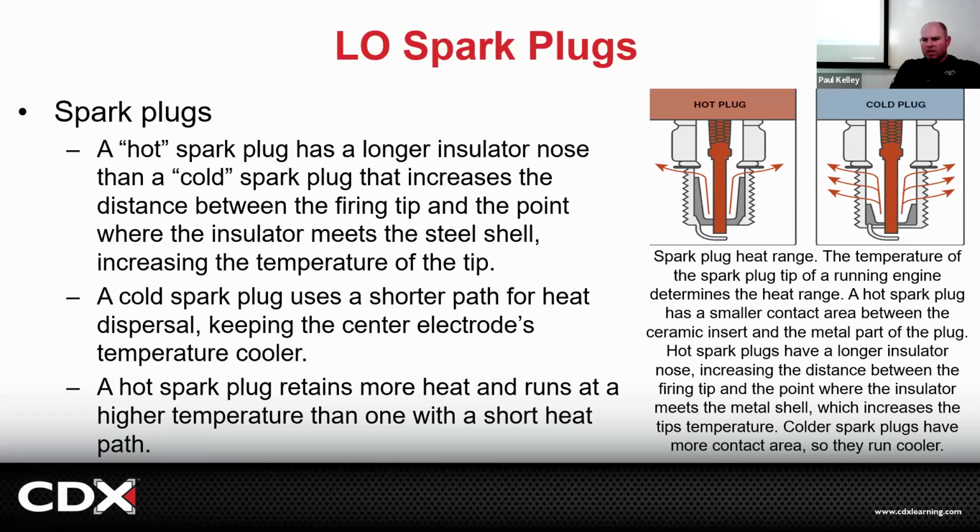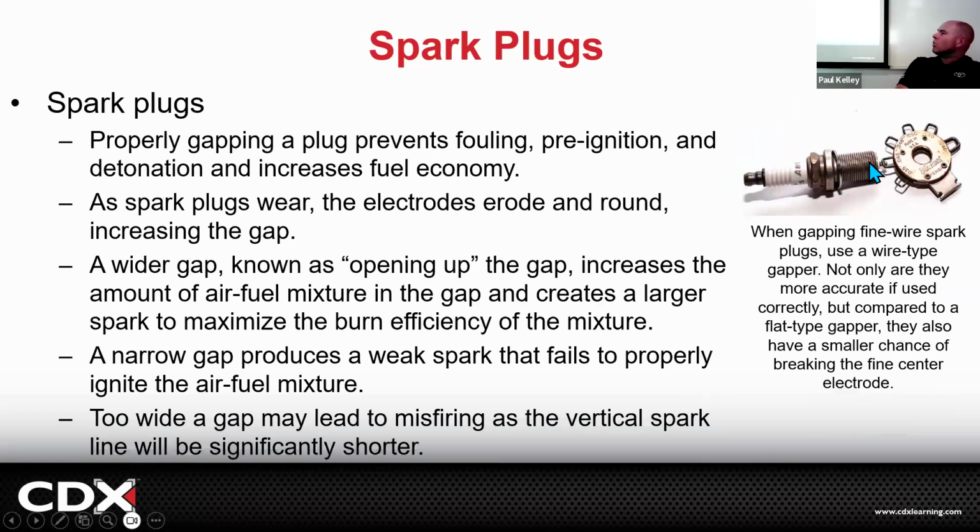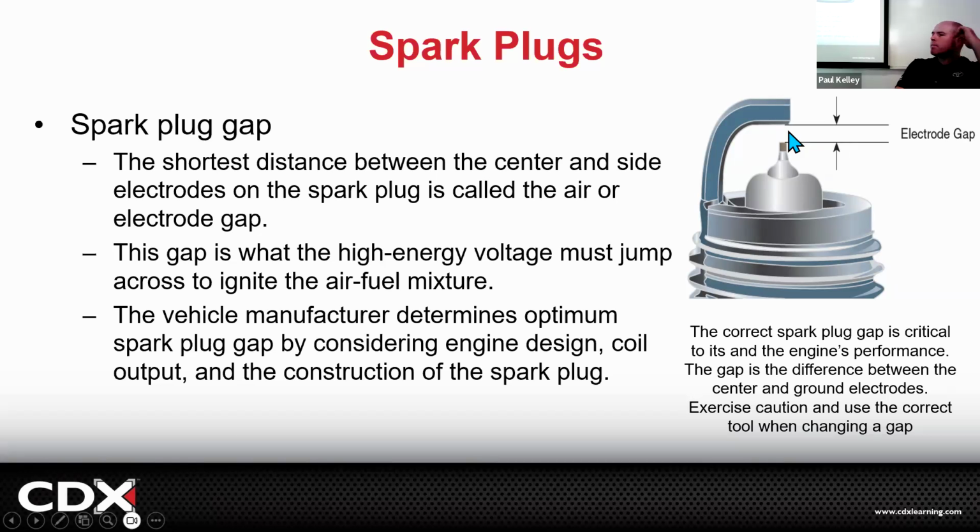All right. And then when we get into talking about this gap, this distance right here is called for by the manufacturer. Has anyone ever gapped spark plugs? Oh yeah, I probably did. So you take the spark plug out and use a little tool like this, and this is a wire type, or they have other designs, and you're going to actually measure that gap. If that gap is too big, that's more resistance. That's harder on your coil, first off, because the voltage, the kV, for the firing line can be high.